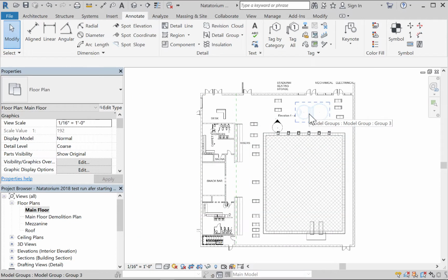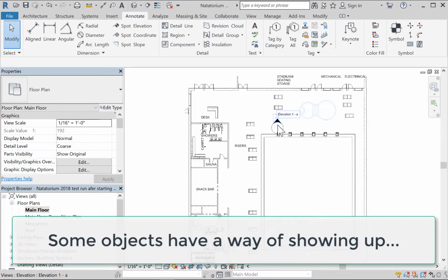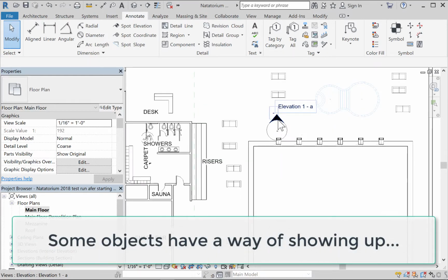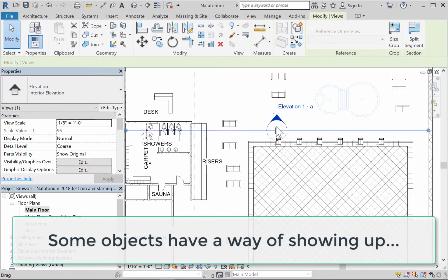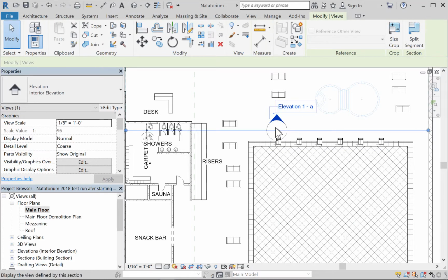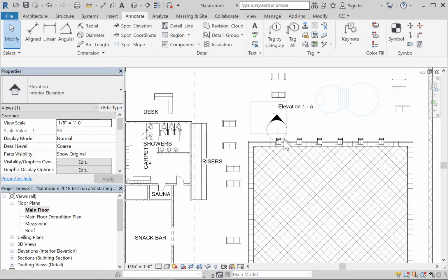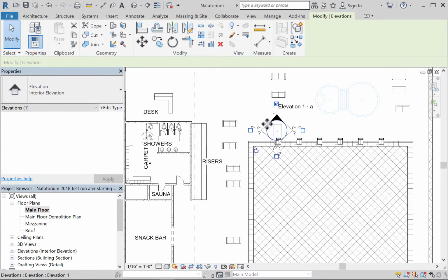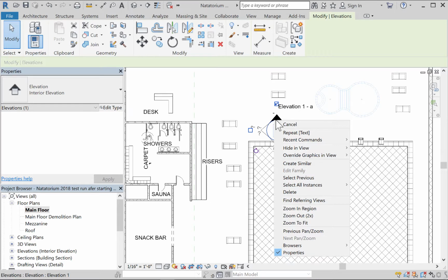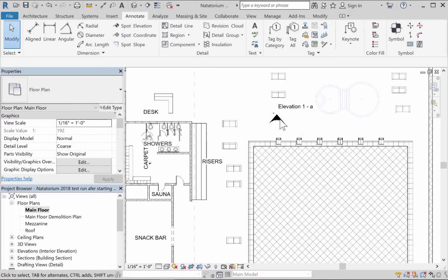Talking about new construction. First of all, oh, hey, my interior elevation from the wrong phase is showing up here. We are going to want to make sure that these little devils don't show up where they're not wanted. So unfortunately, some elements Revit just has trouble knowing how to handle. So I'm just going to hide it in this view. Not the category. Whoops, and this little guy too.